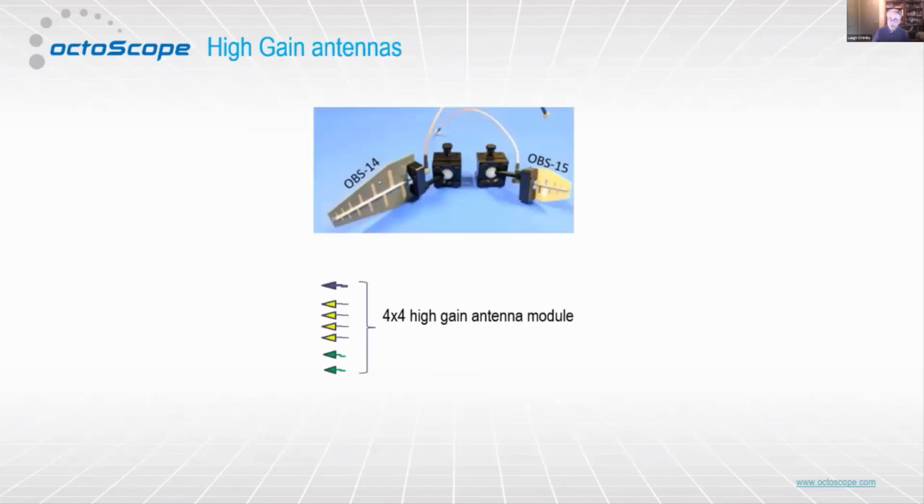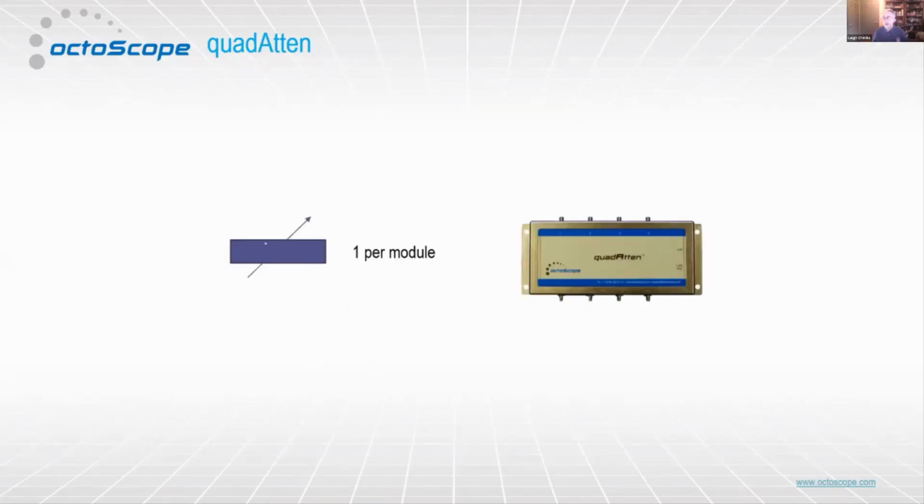You'll see antennas. The antennas are obviously used to connect the devices under test with other devices in the testbed. The key part of our testbeds is that they're over-the-air testbeds. So the device under test is almost always using an over-the-air connection, talking to some of these test antennas. And so when you look at the logical diagram, you see these little arrows. That's what that represents. As the RF energy is moved back and forth between the chambers, it goes through programmable attenuators, and they look like this thing on the right, but they look like this blue box with the arrow through it on the left.